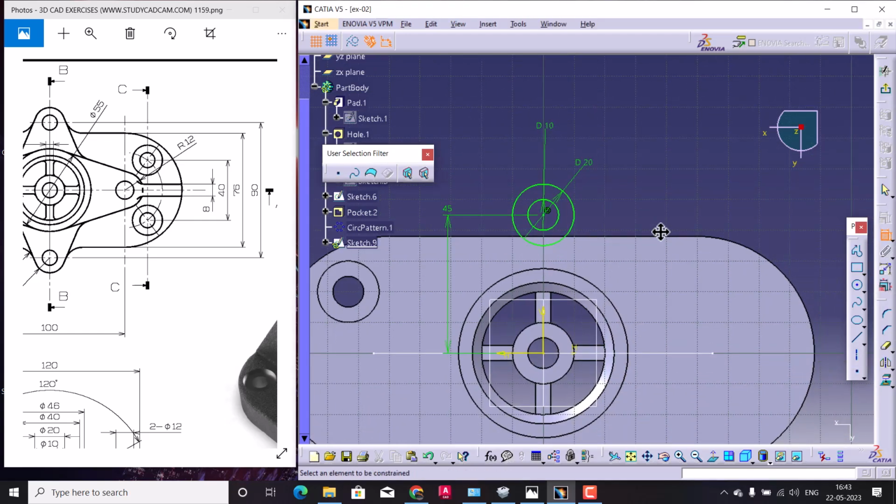Fine. So now you need to connect this. For connecting it, I need a line, but instead of creating the line directly, I want it tangential. So let me project it. Then in line you will have this bitangent line. So select this one and this one, and same thing on the other side.